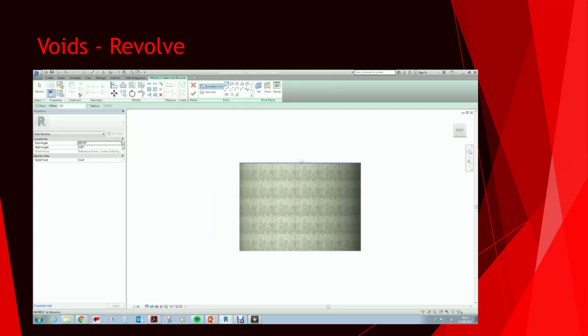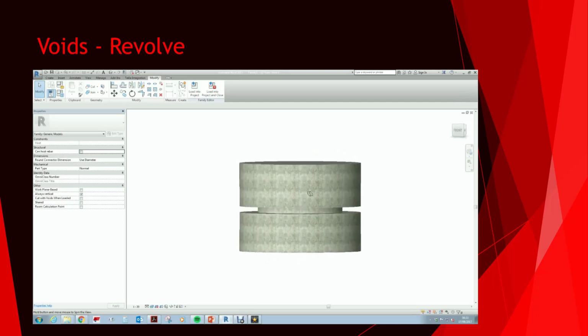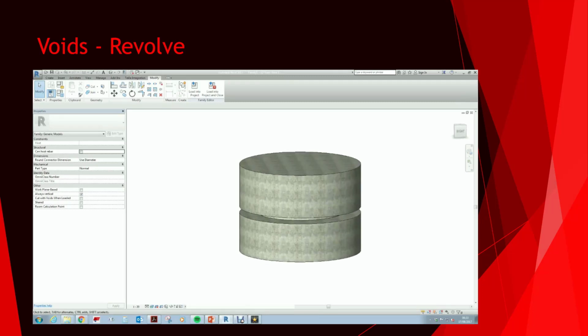Yet again, it's important to sort of clarify what your reference plane is. Once you've got one of the elements in place, say you've got a rectangular or a cube in place with that, you can use that plane. You can essentially pick the front of that face or any face of that element and use that accordingly. So once you've got your starting basis there, you can work around it, pull out, and use the other elements that you've got created afterwards.